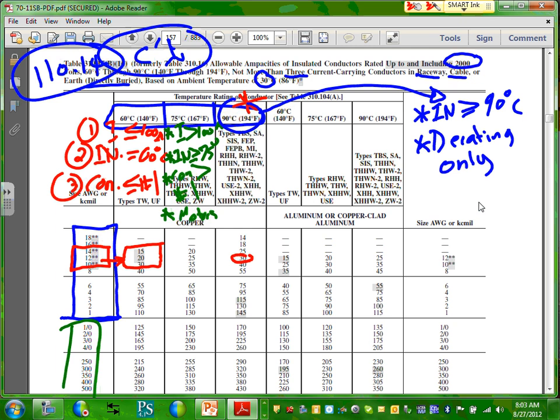Cool. But here's what happened, guys. Suppose I started derating, now for derating purposes, number 12, I start with 30 amps, cut. I end up with 25 amps after I cut. Can number 12 carry 25 amps? No. Why? Two reasons. Number one, because 12 is defaulted to the 60, it cannot carry more than 20 amps. The second reason is that you can't put a circuit breaker higher than 20 amps on it. Small conductor rules. Any question, guys?